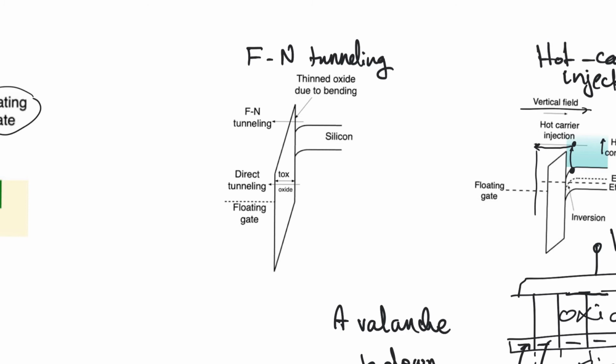So this is tunneling. It's a quantum effect. It's the same kind of tunneling we talked about in module 10. So it does not actually require the physical motion of electrons within the oxide. It is more related to uncertainty and the wave-particle duality of electrons. And when we discussed tunneling, we found that the main determining factor of probability of tunneling is the thickness of the oxide through which we are trying to tunnel, the thickness of the insulator through which we are trying to tunnel. The smaller the thickness, the more likely the tunneling.